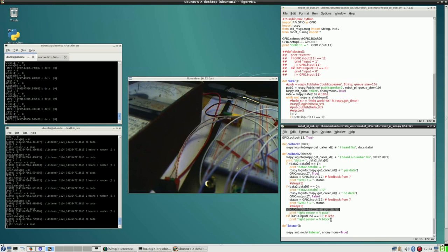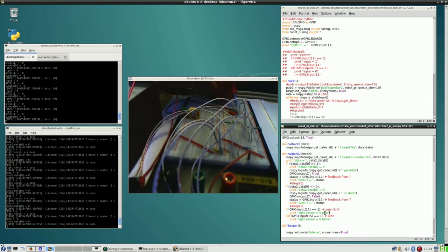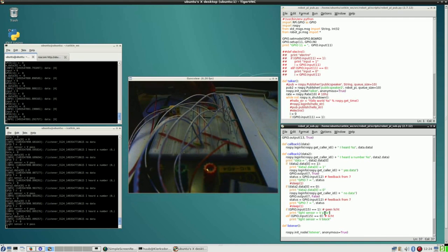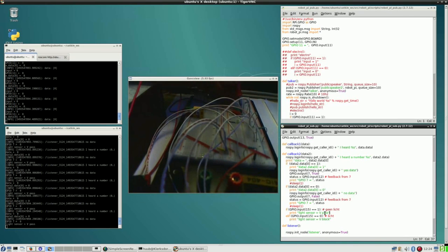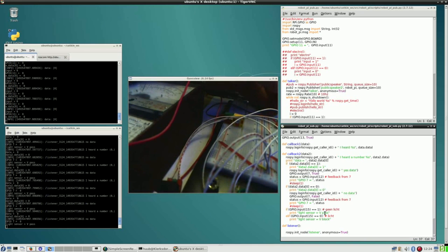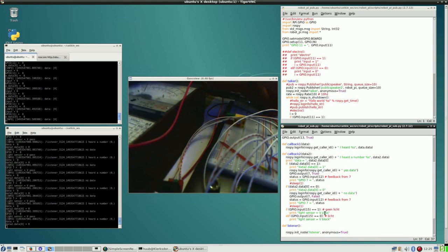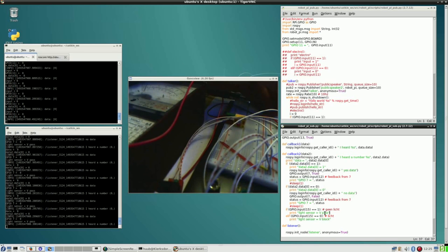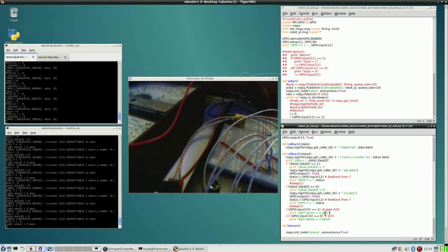This is really exactly directly controlled by the GPIO, but without light there should be 3.3 volts here on the green connector, and looking at the multimeter it indeed says 3.3 volts, more or less, a bit less actually. Which is consistent with no light.